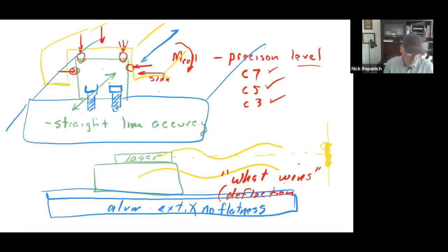We've had projects at the Mechatronics Center. We did a machine where we calculated where we needed that point in 3D space to be. As we worked backwards towards the bearings, we realized the flatness had to be beyond anything that could be done in Chico. We actually found a company, is it Paradise? There's one in Sacramento, one in the Bay Area, that had a machine tool capable of making a flat enough surface that when we mounted our bearing down to it and secured it, it actually got flatter.